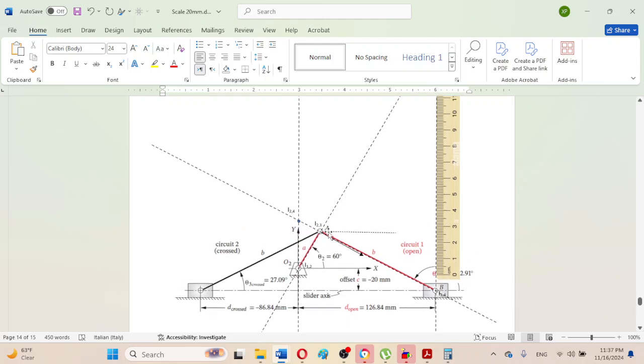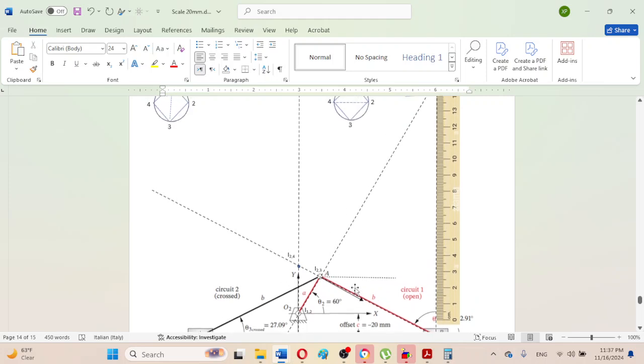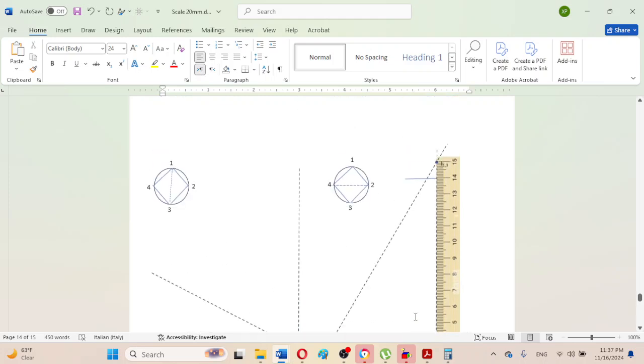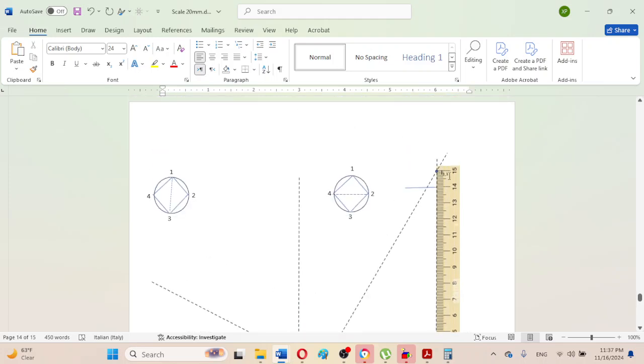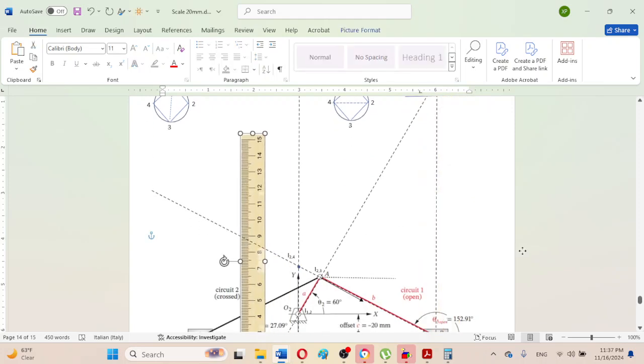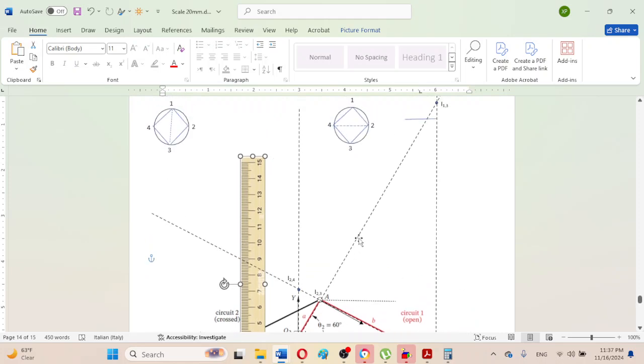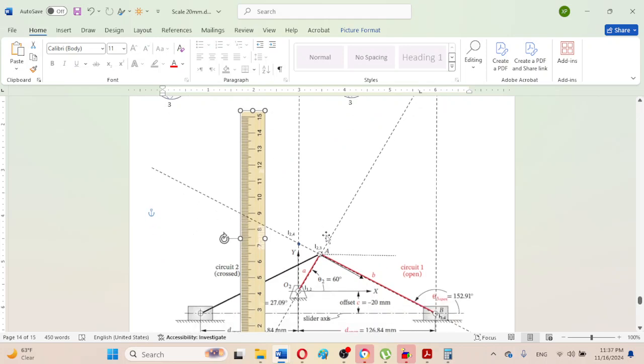So now we temporarily shift this point to the link in complex motion, which is link number 3, AB. Now AB is in pure rotation about this instant center I1,3. So this velocity is, as we can observe here, the center of rotation for the common point on the link AB.